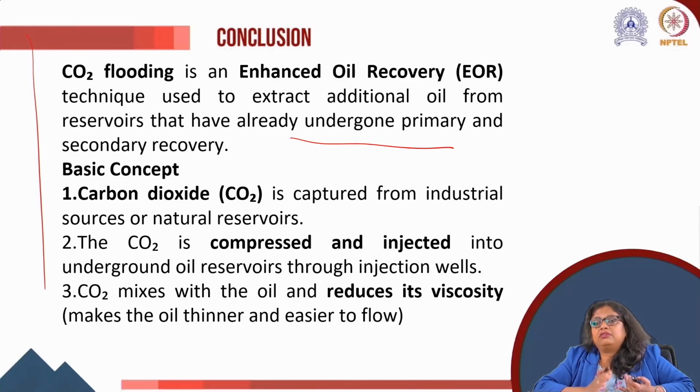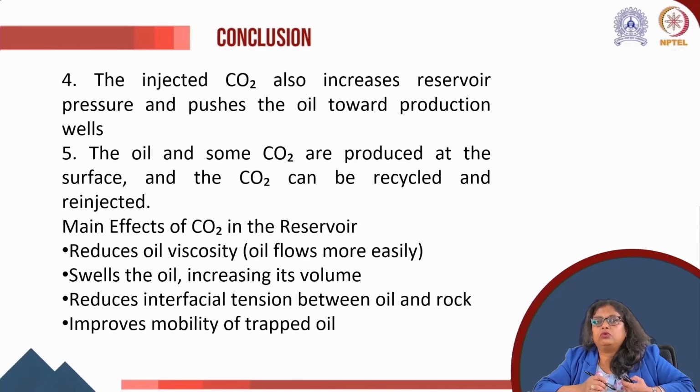CO2 is compressed and injected into the underground oil reservoir through injection wells. CO2 mixes with oil and reduces its viscosity, making the oil thinner and easier to flow. The injected CO2 also increases reservoir pressure and pushes the oil towards your production well. This oil and some CO2 are produced at the surface. CO2 can be recycled and re-injected.